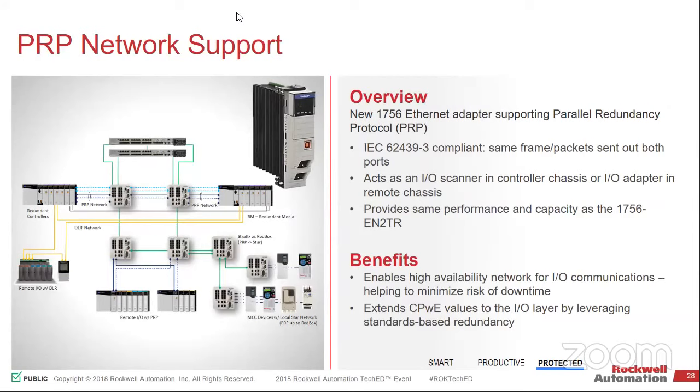Now, these are standard 5700 switches here. Yes. If you want to put a device that doesn't support PRP on it, there are some of the switches, the 5400s, that do support that protocol. And it's not a Rockwell specific protocol. Other people support the PRP protocols. Yeah, it's that IEC numbering scheme, 62439-3, that's what gets called out in the specs, so that would be why we would go after it.